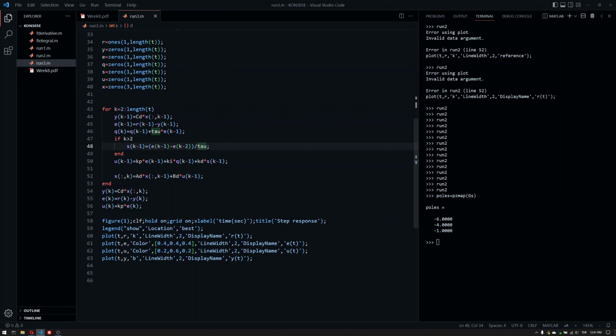If you have used Simulink and if you have encountered an algebraic loop, this is exactly what it was. If we use e(k) and then minus e(k-1), this ends up being an algebraic loop. And if you add just a z to the power of minus 1, or just one sample delay, then you can solve most of the algebraic loops. But you should be careful, because you should know what you're doing. Otherwise, you're just adding z to the power of minus 1 everywhere and expecting the system to work. That might cause some issues too.